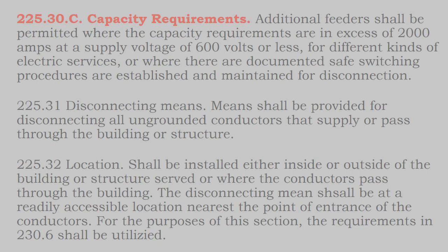And in the past, this disconnect requirement has been very confusing because there's also the utility disconnect, which really, when it boils down to it, says it can be located outside the building or inside at the first available spot. Really what utilities want is a disconnect on the side of the building that they can use to turn off your on-site power systems. And maybe that'll be multiple disconnects for when you get into having a solar array and an electric vehicle charging station, something like that.